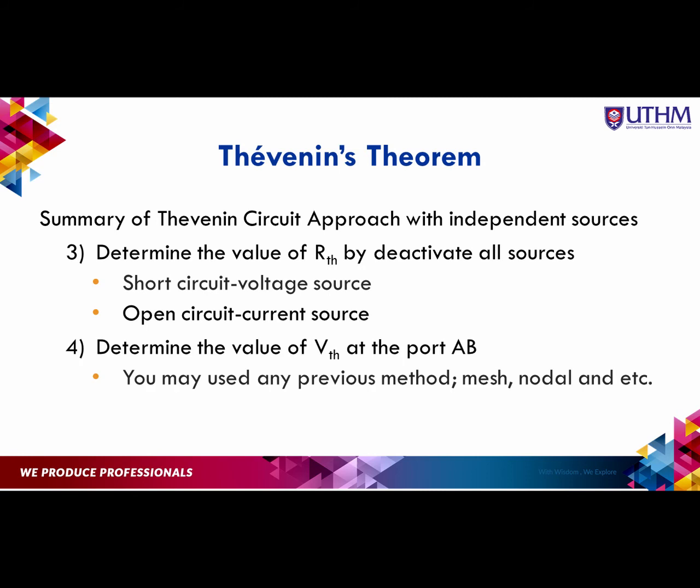And for step number 4, we calculate and determine the value of Thevenin voltage. In order to do this, you have to calculate the voltage across port AB, from the point of view of port AB. So you can always use the previous techniques that we have learned, such as mesh, nodal, and any other technique in order to determine the value of Thevenin voltage.